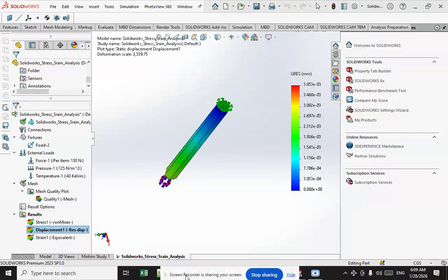Graphical representation of stress at a point. Mohr's circle, Lamé's stress ellipsoid together with the stress director surface, and Cauchy's stress quadric are two-dimensional graphical representations of the state of the stress at a point. They allow for the graphical determination of the magnitude of the stress tensor at a given point for all planes passing through that point. Mohr's circle is the most common graphical method. Mohr's circle, named after Christian Otto Mohr, is the locus of points that represent the set of stress on individual planes at all their orientations.